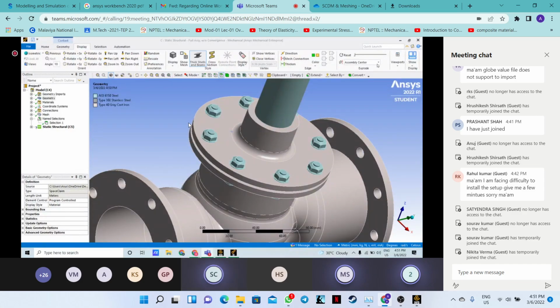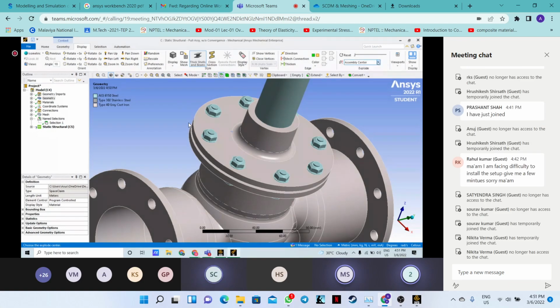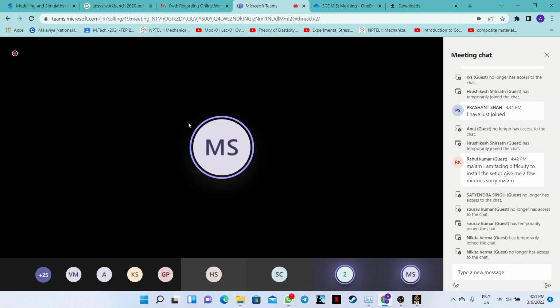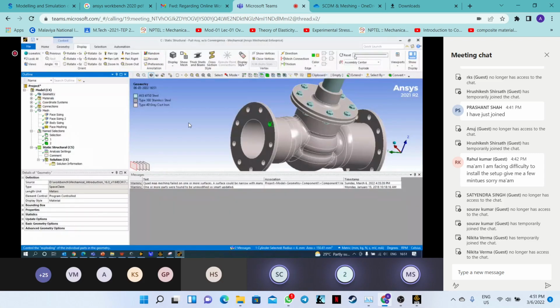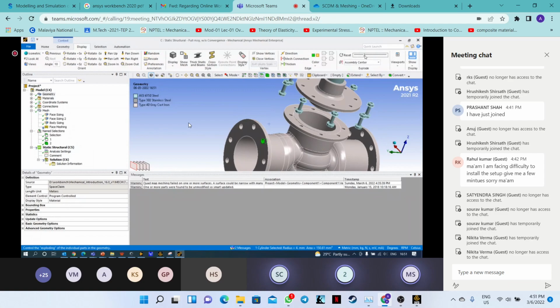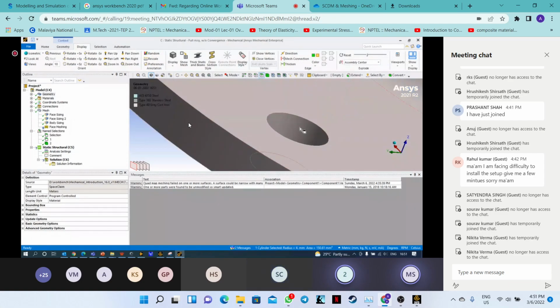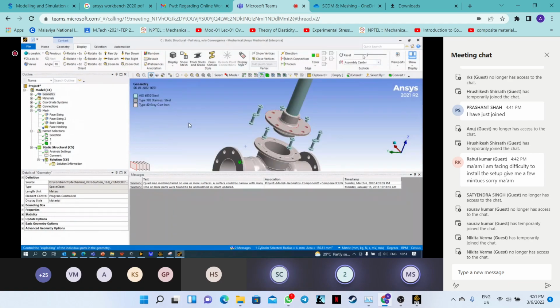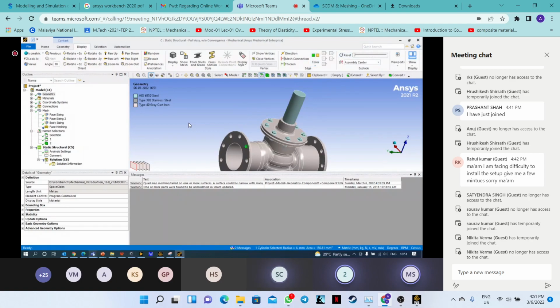Above that you have reset, right? Just scroll that, move that. You can see a button, right? Just you have display, and click on your geometry and reset. Yes, ma'am, that way you will be able to select the hole. Done. Okay, ma'am. Thank you.